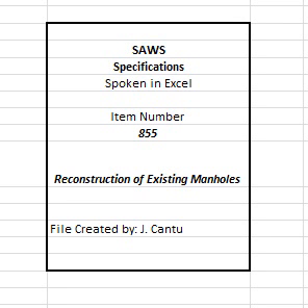B. The I/I barrier shall be as manufactured by Strike Tool Products of Cannon Falls, Minnesota. C. SAWS APL. Throat rings are limited to a minimum of 2 and a maximum of 4 rings for reconstructed manholes. D. Throat rings shall be a maximum thickness of 2 inches.